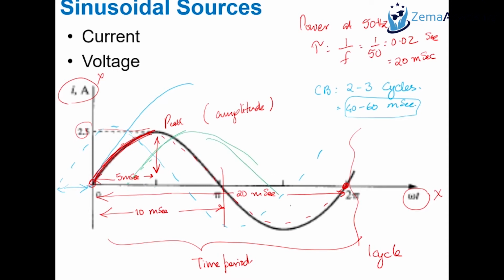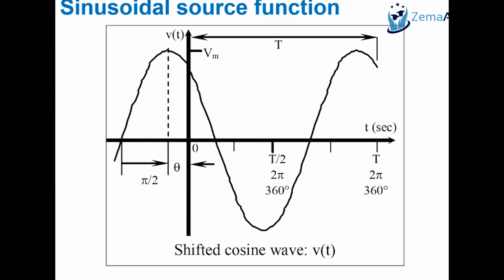So you can have a waveform that starts after a certain time delay. So it's all about where the waveform is starting. If sine is not starting at time t equals 0, it can start after a delay, or it can start ahead of the starting point. And that is what is related to the words lag and lead, and that's associated with the phase angle. So often you call a phase angle lag or a phase angle lead, and therefore lagging power factor and leading power factor, which are the terms you'll become familiar with later on. So that's how you can do the shifting.